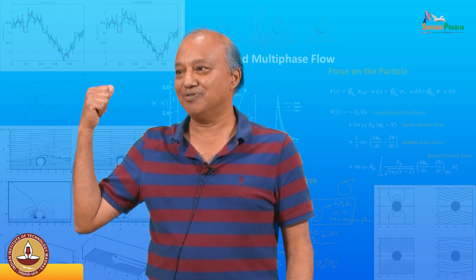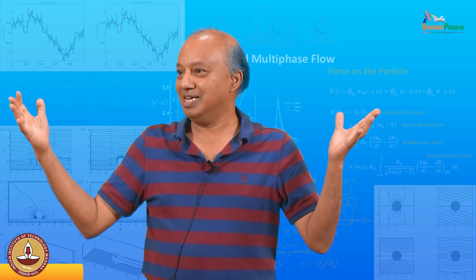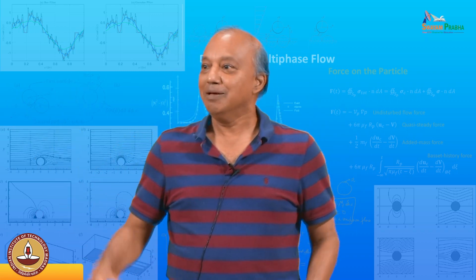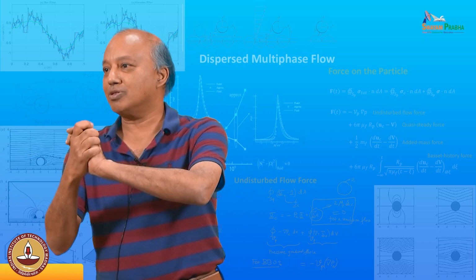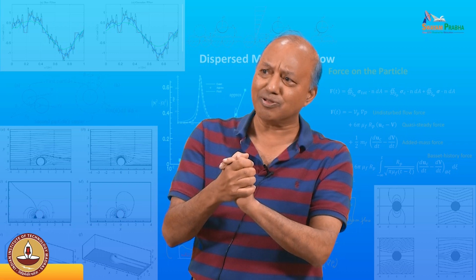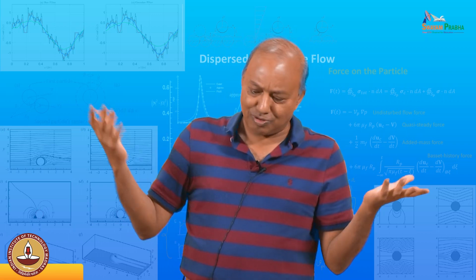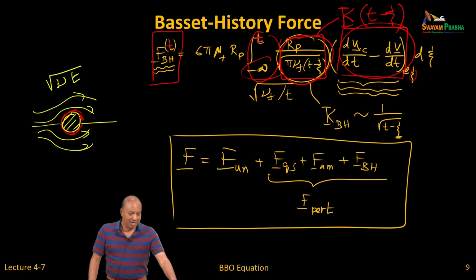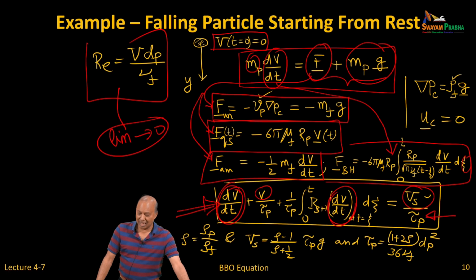You just have to do this integral and you have the force, and it is exact in the zero Reynolds number limit. That's because they have encoded all the fluid mechanics at the small scale, taking into account the perturbation, and the answer comes out to be this complicated term. Now, the Basset-Boussinesq equation was from 1883 or something like that.